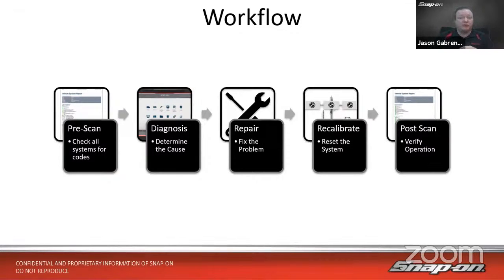So you want to make sure that you check and perform any resets, recalibrations, relearns that need to be done for that repair for that vehicle. And then after that, we'll clear the codes. We'll take it for a road test. And then we want to make sure that all of the readiness monitors are set, because once those readiness monitors are set, then we know we won't have any at least emissions-related codes, because that's what the monitors are there for, to check for that.